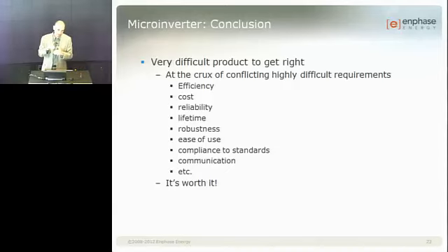The problem I had is that each of my microinverters was actually compliant, but the more you add, the more the noise floor goes up, right? And they didn't expect that. So it was working fine at night, but not during the day, which is a bit of an issue because that's when you want the data. So we had to get away from that noise floor issue, and we couldn't use that technology whatsoever. We had to do something entirely different.